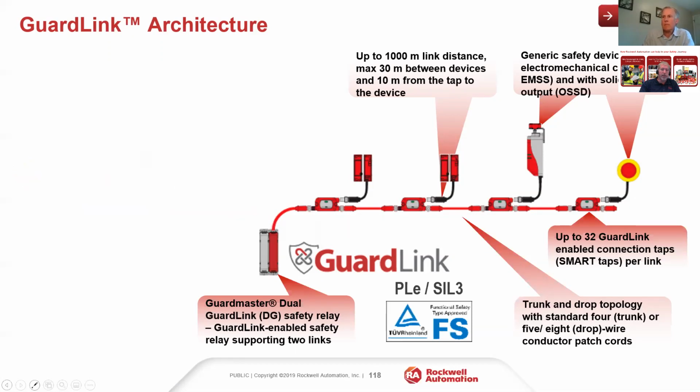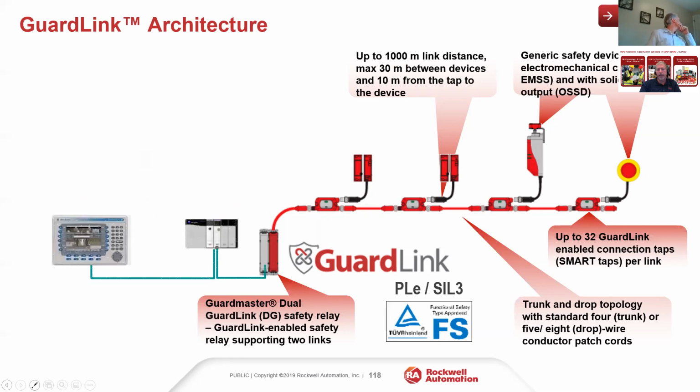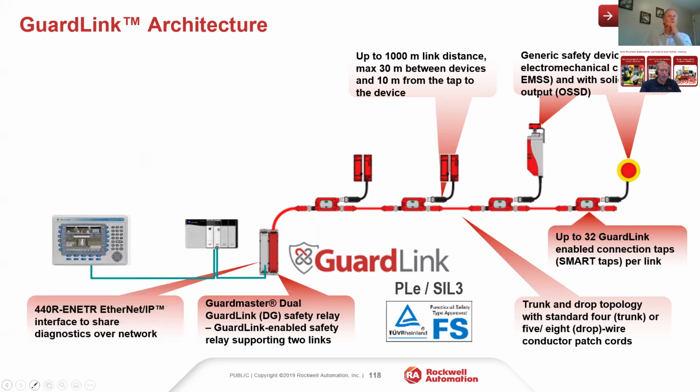The beauty of it comes in is that we have an EtherNet/IP interface that will optically connect. There's an optical bus on the back that connects, and we connect that into our Logix controller, a standard Logix controller. This is a gray box, not a red box. So this is providing us diagnostic information, but not safety. Safety is managed by the relay, but the diagnostic information is provided as to which switch in that trunk of 32 or 64, which switch actually is opened, okay?